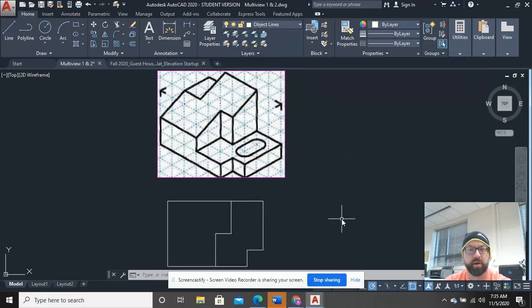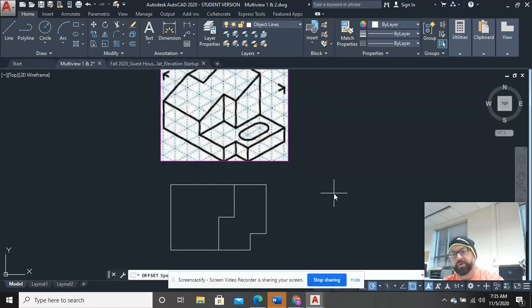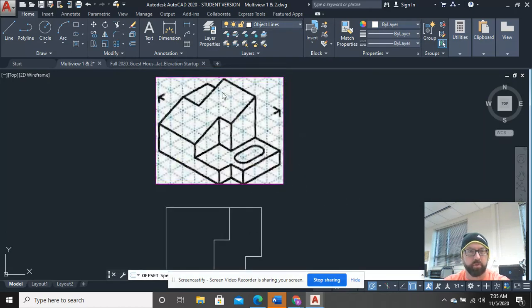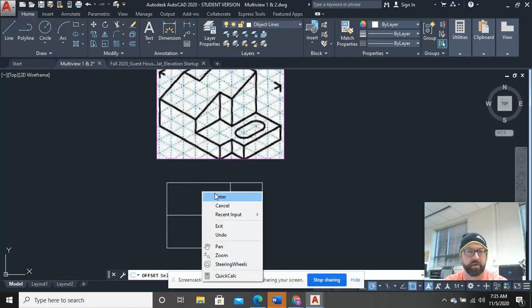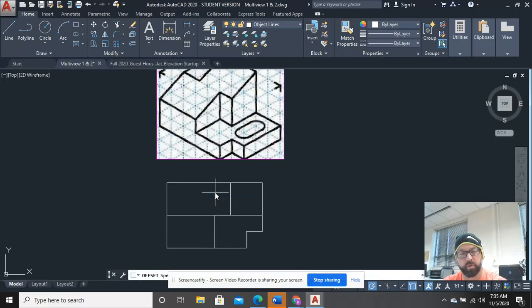So in this case, I'm going to go back to using my offset. Okay, and I'll go back to object lines, and I go offset, which means that I can go, let's see, over 1 and forward 2, right, from the back. So I'll go offset 2 from the back. Oh, look at that. It puts me on that exact same line, and then offset over 1. Okay, it's looking goofed up again. We've confused ourselves a little bit, right?